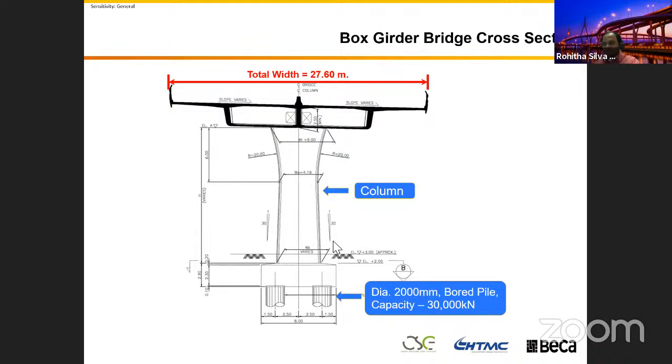You can't just use this solution. Then you need to find a different bridge solution. If your foundation is really stiff and you try to push the creep shrinkage forces, this area will crack at that interface. So we come up with different solutions in bridge structures according to their behavior.